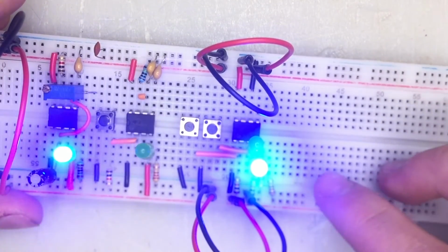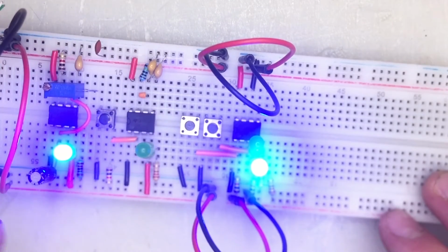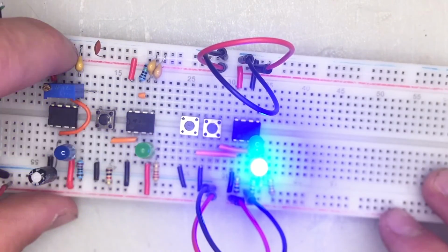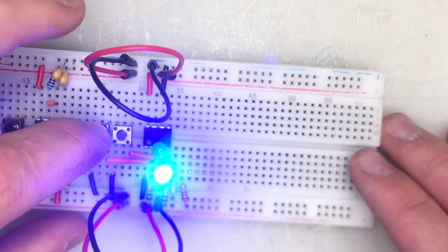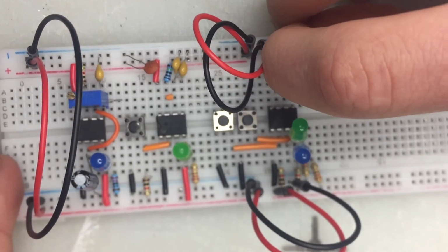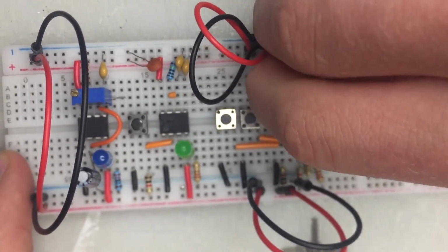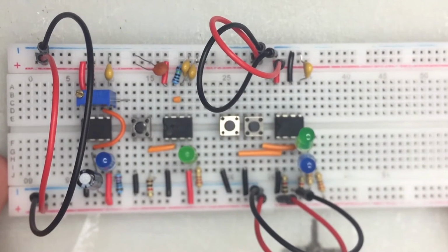So now everything works. When I push one button, one LED turns on. When I push the other, the other LED turns on. So that's all working good. And the reason I did this is just to make it easier to see what mode we're in. And I forgot to add a 0.01 microfarad capacitor in between ground and pin 5, so I'll do that now. And now the circuit's fully complete, I'm ready to build this on EasyEDA.